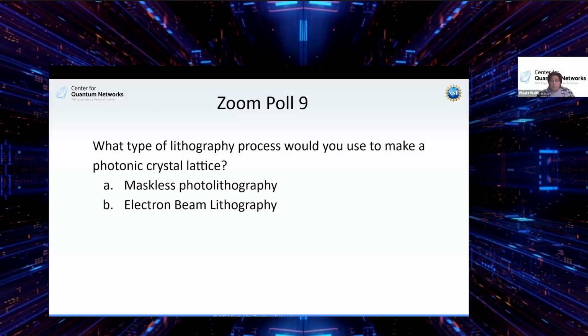I wouldn't deny there are examples of someone using a photomask with photolithography, I could see that being used maybe in some applications. But if it's maskless versus e-beam, no. Mainly because those nanopillars, especially if they're cylindrical, the dimensions I've seen on those are usually on the order of 10 nanometers, sometimes 50 or 60. But they're definitely less, and especially if the shape of those pillars is very important, whether they're square, hexagonal, rectangular, or cylindrical, that makes a very big difference.